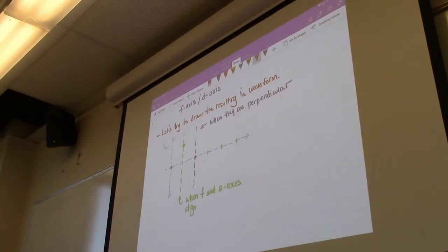And then over here, we'll have another instance of them lining up because, right, the coils are not directional, right? They can line up like this or they can line up like that. However, it will have an effect on the polarity, right? Because it'll be flipping the direction of the terminals with respect to the field winding, right? If we have it like this in the beginning, IA is positive with respect to IF, and if you go over here, IA is negative.